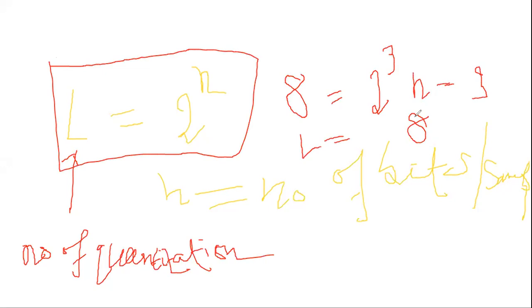So what terms did we get? Number of quantization level. Listen everyone. Okay, number of bits. What is the relation between the number of bits required to code each and every sample? That is n, and 2 to the power n is nothing but the number of quantization levels required to quantize the signal.